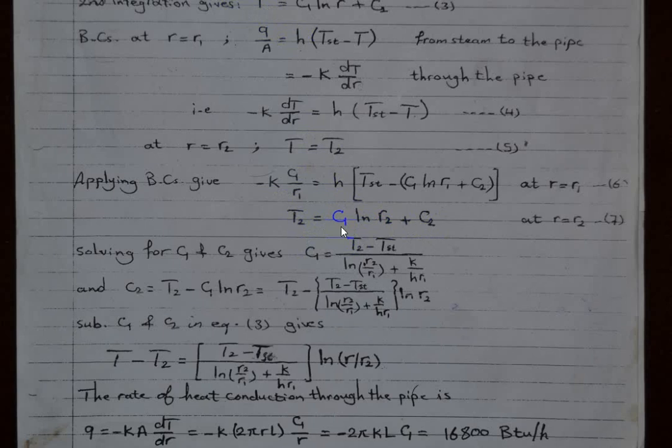At the outer surface of the steam pipe, as you can see, but at the inner surface, right between the steam flowing through the pipe and the pipe itself, the steam is transferring heat to the pipe by the convection mechanism, while from the inner to the outer surface of the pipe the heat is transferred by conduction.